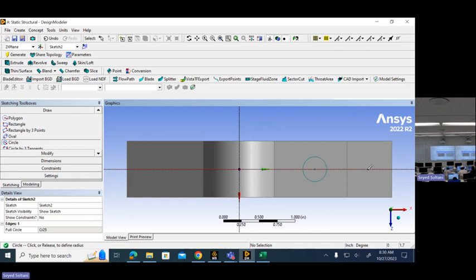And here's another one. See, when you're drawing the second circle, you see this option here shows R. When you see this letter showing up, it means that essentially these two circles would be of equal radius. So you are adding a constraint automatically to your drawing, which is a good thing. In this case, it's actually helpful. So we're going to see how it works.